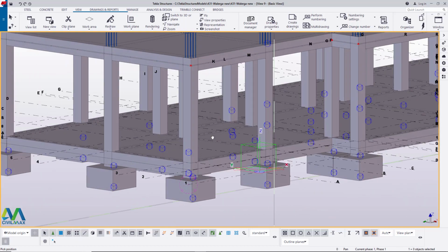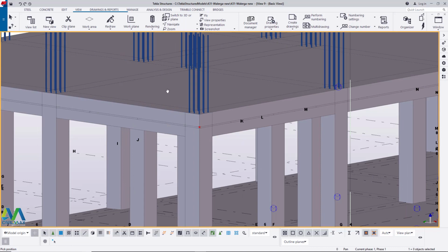Now we've laid our panels. And remember, when laying the panels, the concrete is not always in place before. But in this case, we are putting the slab so that the panels pick the profile of the slab that will be cast on it. So usually the slab is not done prior to laying the panels, but in this case, we are using the slab to enable the panel to follow the profile of the whole slab on top of our building.